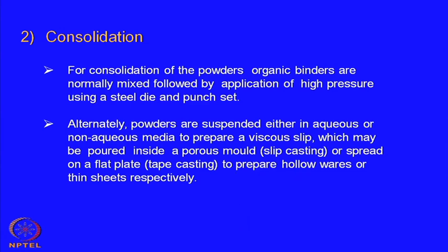You control the porosity, and because of capillary action, the water in which the particles are suspended is preferentially absorbed, soaked inside the pores, and the powders form a skin on the surface of the mold.